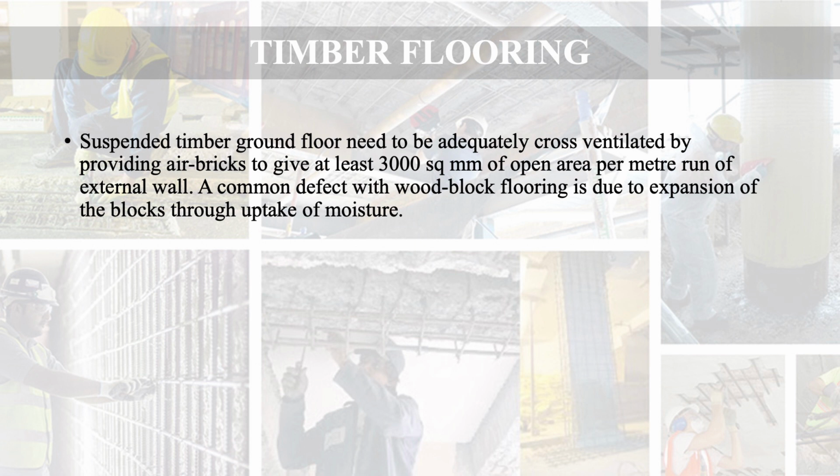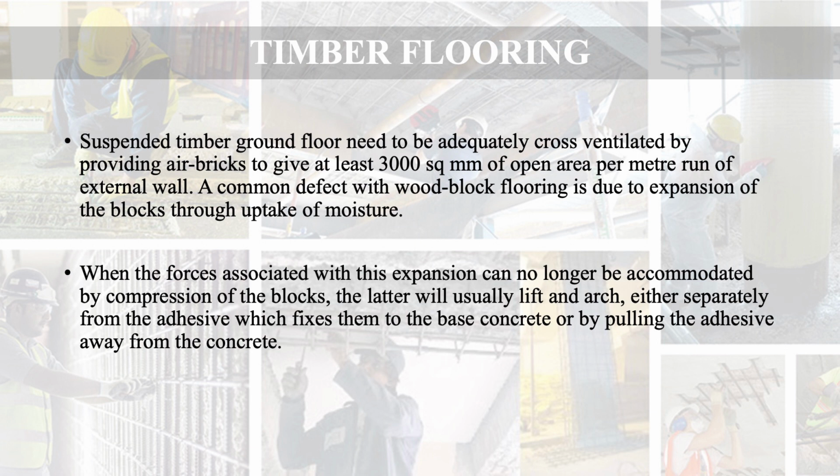A common defect with wood block flooring is due to expansion of the blocks through uptake of moisture. It means by absorbing moisture, there will be expansion of the blocks. When the forces associated with this expansion can no longer be accommodated by compression of the blocks, the latter will usually lift and arch, either separately from the adhesive which fixes them to the base concrete, or by pulling the adhesive away from the concrete. So these are the two possibilities.